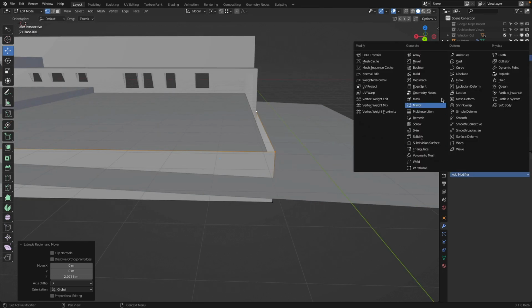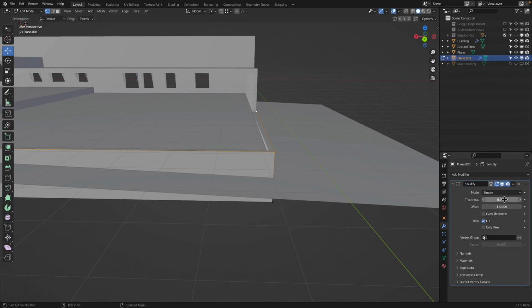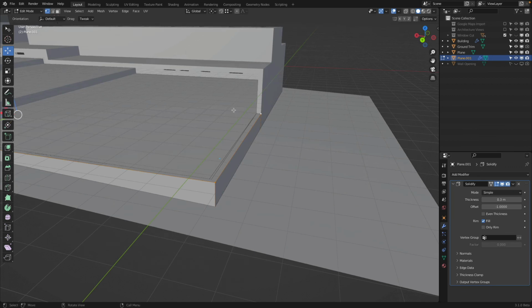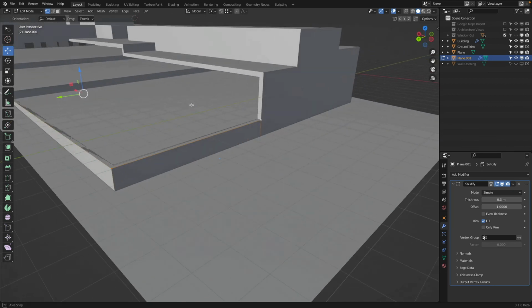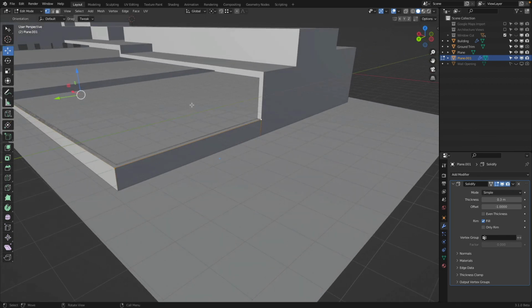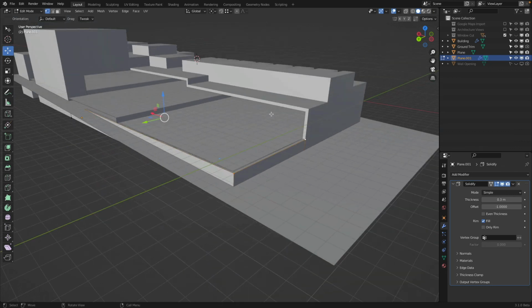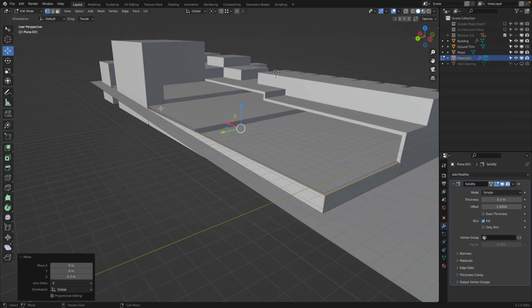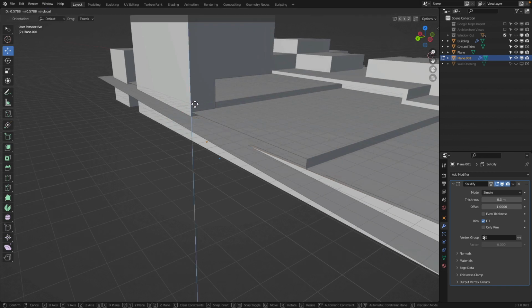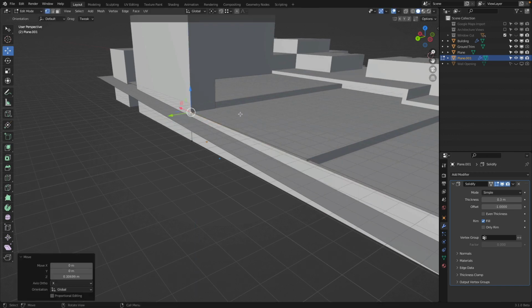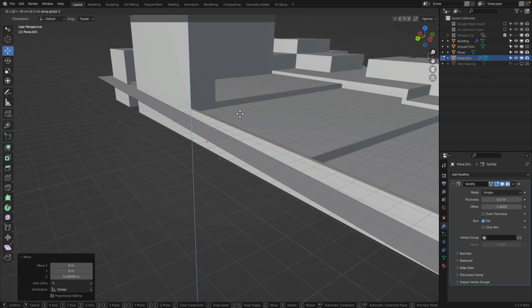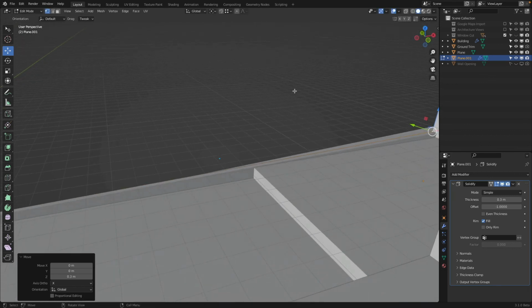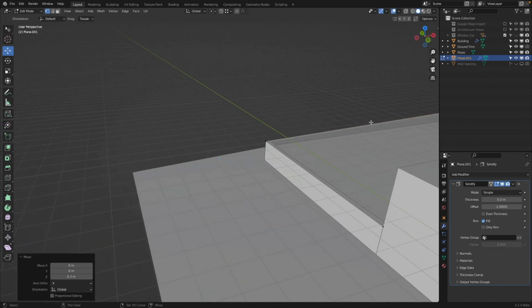We could give this a material thickness. We give this the same as the wall there. And then how do we bring this up a little bit more? Let's say 30 centimeters, GZ 0.3. Very good. But you see now, well, there it doesn't cut it, but we can bring this to there, move this up and snap, and then another GZ 0.3. So this is now 3.